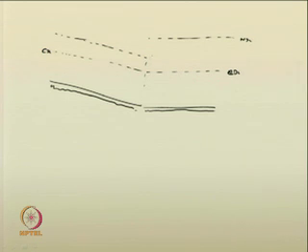See, there may be a chance that normal uniform flow exists up to this point in channel 1, and from here a curve goes and merges with the normal depth line, that is the water surface profile. From here it will just go like this and reaches the normal depth line, means the water surface profile goes in this way. You can imagine like that.